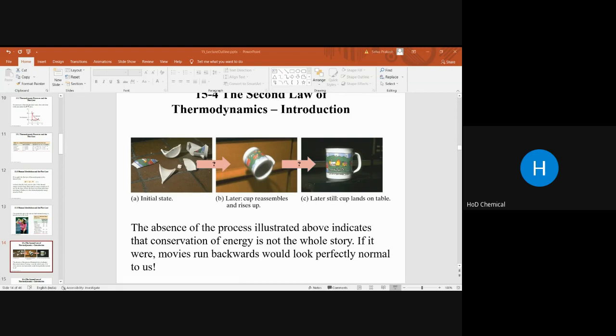Now, using conservation of energy to eliminate W, we find that the work is also the heat transferred, QH minus QL. We can derive the equation: e equals W divided by QH.